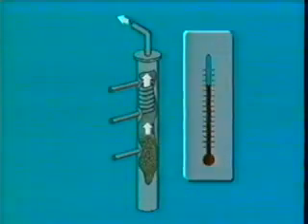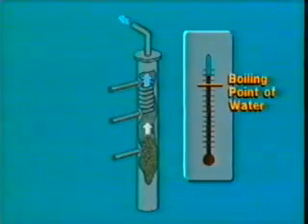If the still overhead temperature is above the boiling point of pure water, glycol carryover is the result, and losses will be higher than normal. If the still overhead temperature is below the boiling point of pure water, too much water will be condensed back into the glycol. This will cause both the reboiler heat requirements and fuel usage to increase.